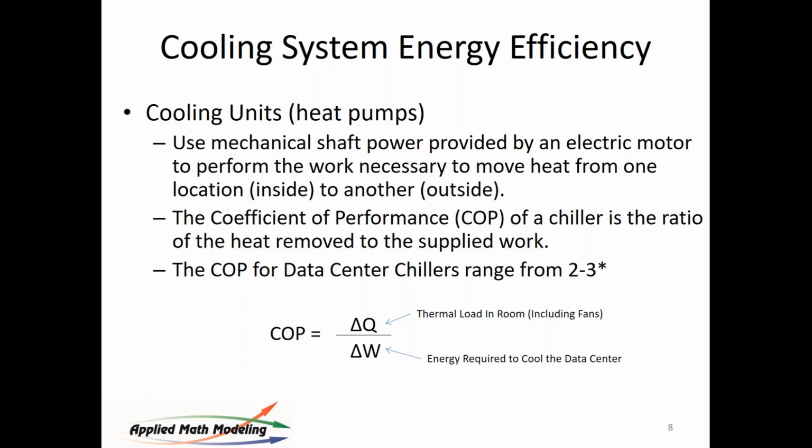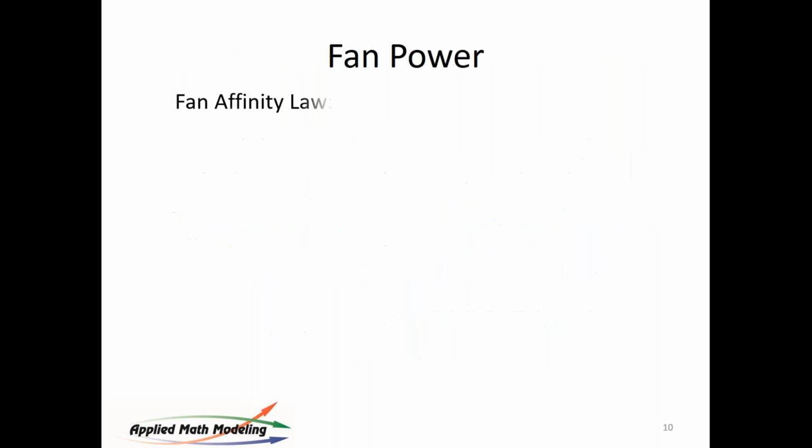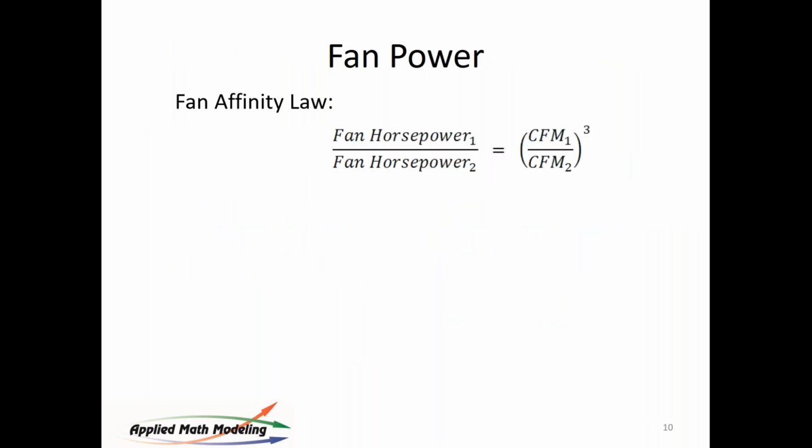This is just the mechanical component. As you know, this is not a constant. It changes over the course of the year, and it changes as a function of geography. But we have to make some assumptions in order to design, and so we have to come up with an average COP for the year and then do analysis based on that. And that's what we'll do for the analysis we're going to do here today.